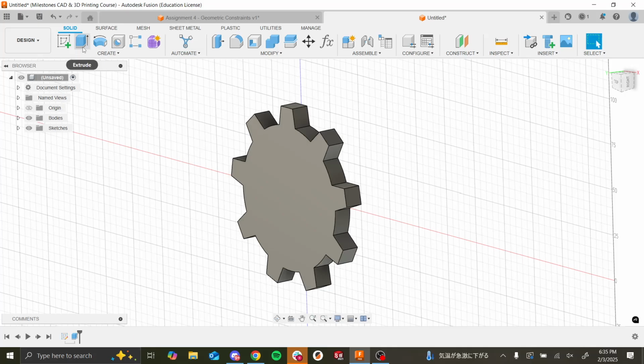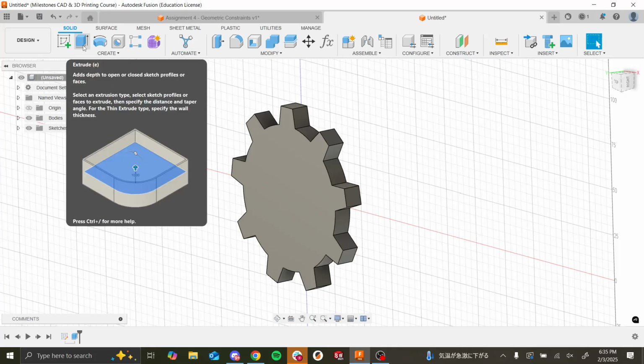Especially when it's a CNC part, people will use computers to program a machine to make your part, and Fusion can use the hole data to select certain tools and stuff like that to create it. But if you have it as an extrude, the software will think of it as a pocket instead of a hole.